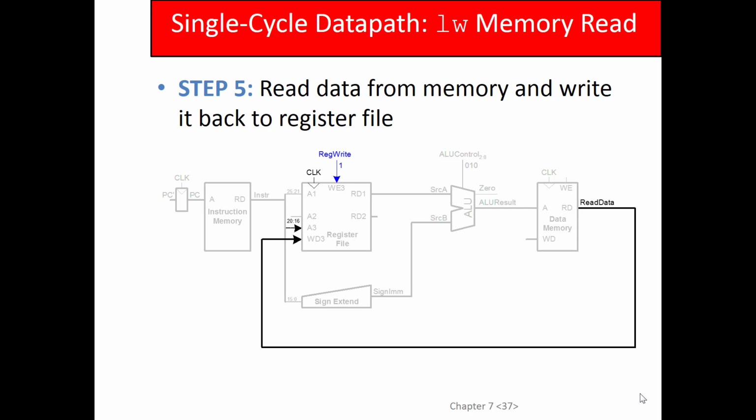Right? Everything, oh, and stores. Stores store to the memory, they don't store to the register file. Branches and jumps just manipulate the program counter. Everything else has to write its result back to the register file. Right? Including load. So what are we doing with a load?